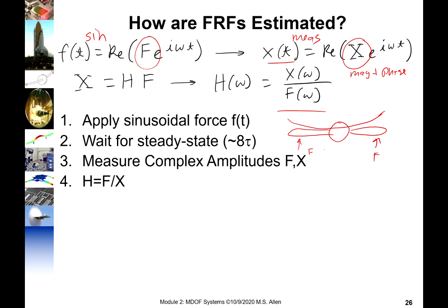And this is actually frequently done in the aircraft industry. They'll drive each mode to resonance and use this approach to calculate the transfer function and to calculate the damping at resonance. And it's robust to nonlinearities, so things like slip in joints, in flaps, wing flaps, things like that, don't tend to perturb this method.